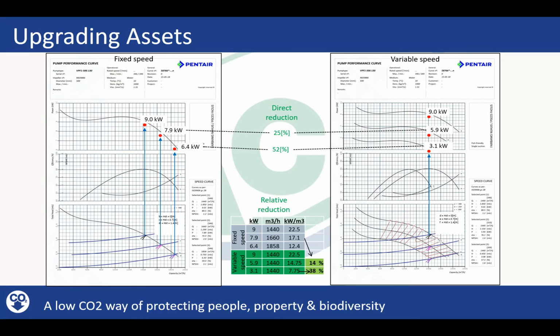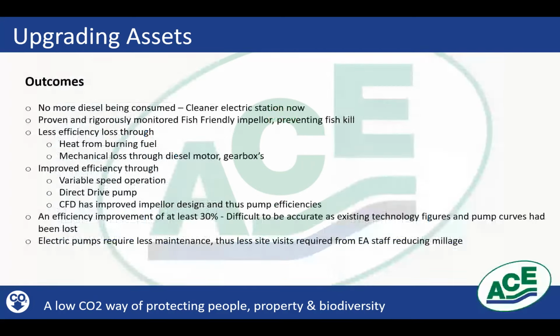Now, in a lot of pumping stations, you actually pump on the lower flows more frequently than the upper flows. You've got to think that the pumping station has been designed for a flood situation, the worst case. That's where the duty points are quite often drawn up. The reality is you're actually often just taking the cream off the top, if you like, making sure the drain is maintained at that particular level. Frequently, this is being done at a lower volume, at a lower flow, so at the bottom end. So you actually end up spending more time pumping down here than you would up there, which further means that the energy savings through these variable speed drives are absolutely enormous.